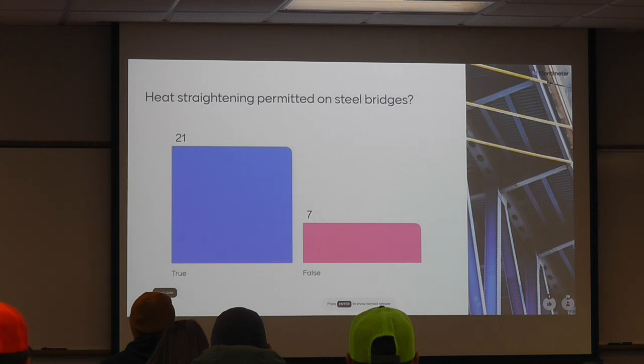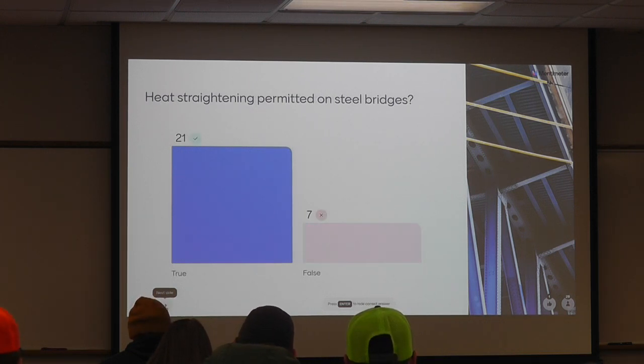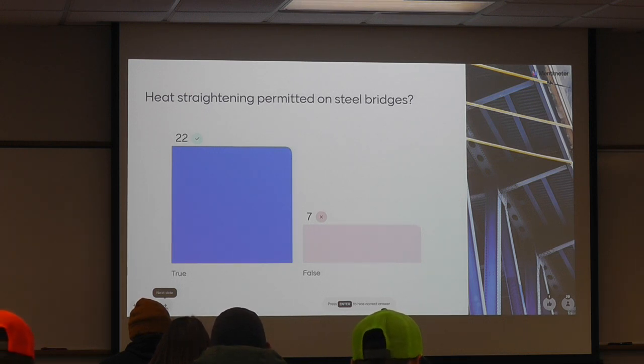That is the correct answer, with the caveat that it has to be approved by the engineer once we've accepted their plan. Right? But we do permit it. In fact, when we get our bridges that are in service hit by an overheight load, very often we're going up there and doing that, especially if it's a steel bridge, versus cutting the girder off and replacing it.